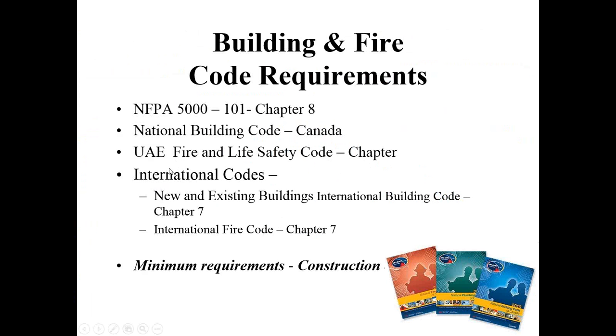The only standard that's not in the National Building Code of Canada's ULC S115 is the perimeter fire containment assembly. That perimeter fire containment assembly, the ASTM E2307, is something that's specified in Canada for curtain wall type joint assemblies for the testing.